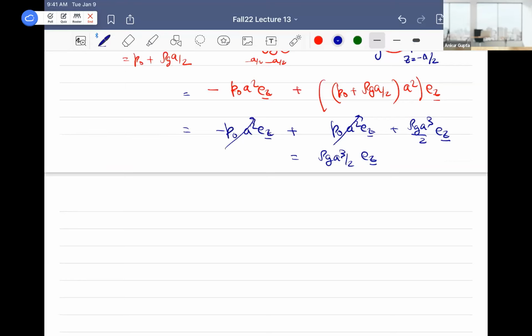Yes, please. Would you also, as another method of approaching this, be able to do all of it at once and just use the divergence theorem? Yes. So that's essentially the derivation of Archimedes principle. So instead of actually trying to do minus P and grad P and dS, you can convert it into a volumetric integral using the divergence theorem, and you will essentially get the answer.